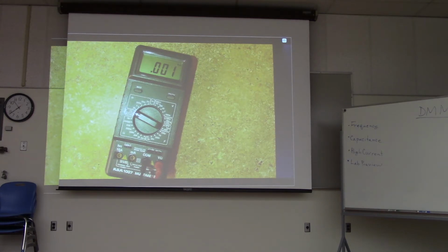So you're going to turn the amplitude all the way down on the function generator, so it's creating almost no voltage. Then you're going to hook up the LED, and then you're slowly going to turn the amplitude up until you can see the light, until it just starts getting a little bit bright enough for you to see. Right? If you start with the amplitude way up, you can burn out the LED, and it can actually explode, which is not good. So you're going to start with the amplitude all the way down, and then slowly turn it up until you can see it.